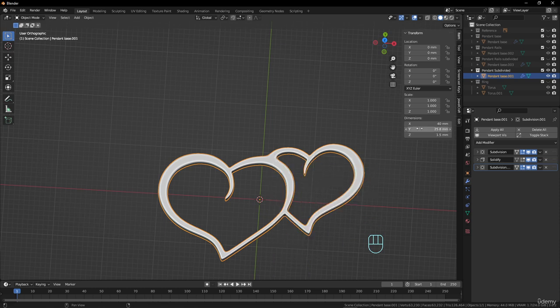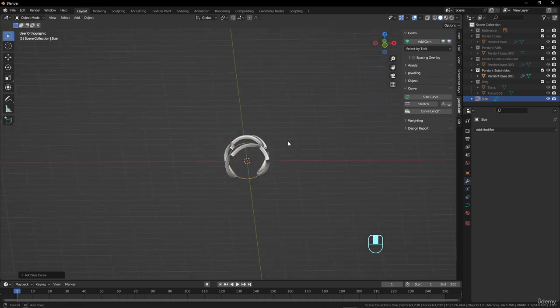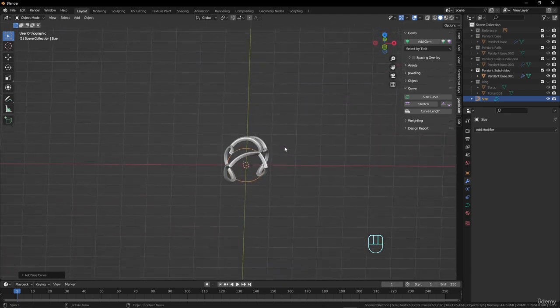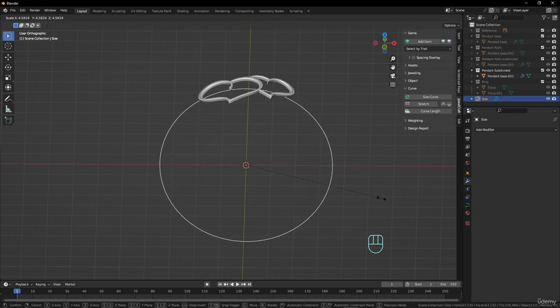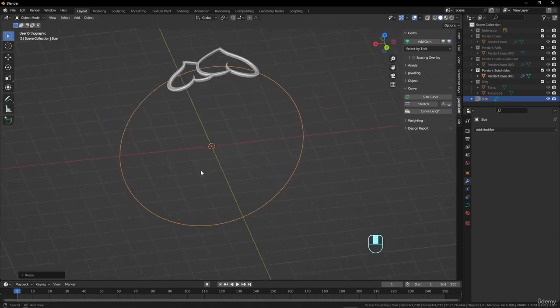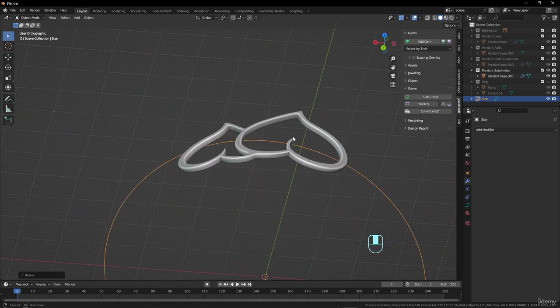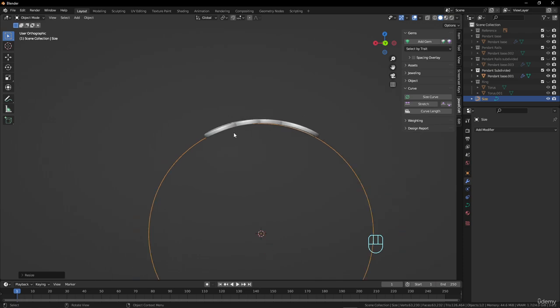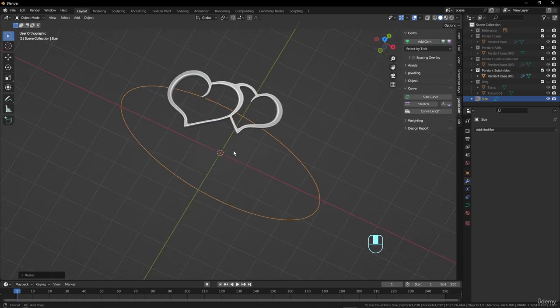So let's say we will add, like usual, into the Jewelcraft add-on, we will add a curve here, a size curve, up, and you can see that this design now is around the curve. So you can scale it up, for example, scale up the curve like this, and now you have what you want. Okay, so the design is not flat but a little bent like that. So it can be useful sometimes for having multiple designs.